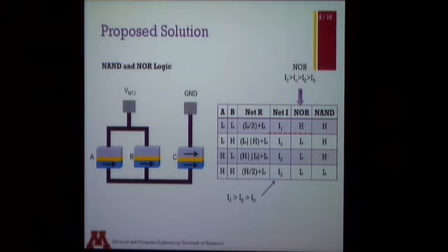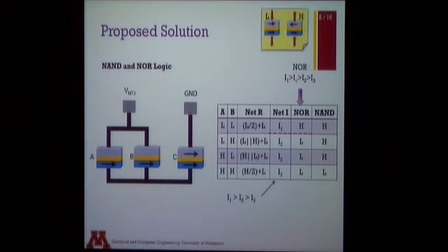So if we can engineer this particular value of the applied voltage so that I1 is greater than IC greater than I2, then we are able to cut off the truth table at this particular point. Since I1 is greater than IC only for the first particular case, the current that flows from bottom to top writes a logic 1 to this particular MTJ. So here's your cheat sheet back. When current flows from bottom to top, you get a logic high over here.